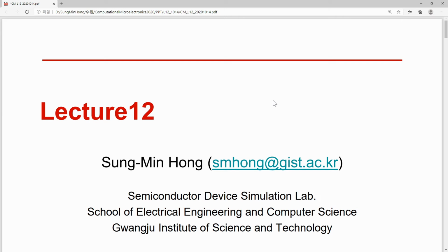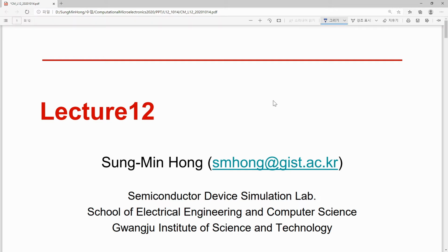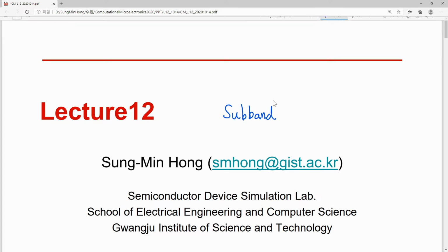Hello everyone, this is the preview lecture for lecture 12. In lecture 11, the previous one, we have studied the concept of subband. And today we wanted to calculate the electron density by using the Schrödinger-Poisson equation, but not in a fully consistent way, but in an inconsistent way.